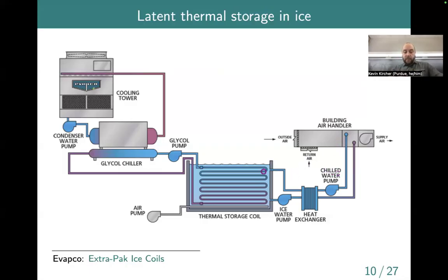So here we're extracting chilled water, I guess, pumping that through a heat exchanger, and then there's probably a closed loop of chilled water that circulates through this air handling unit here. This would be pulling back warm return air from the building, mixing in some outside air, and then blowing that fresh mixed air to the building. I actually don't know what purpose this air pump serves.